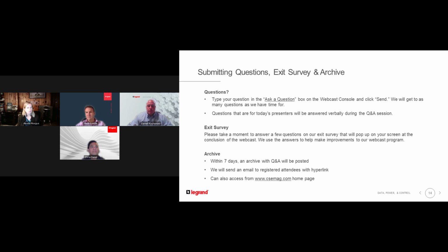When we track that down, we find out that the busway was cut smack dab in the middle with an end cap put on the end of it, right? If we were to energize that, that would see some serious issues, right? So we want to make sure that we abide by all those creepage and clearance rules, and that we aren't cutting that in the field.